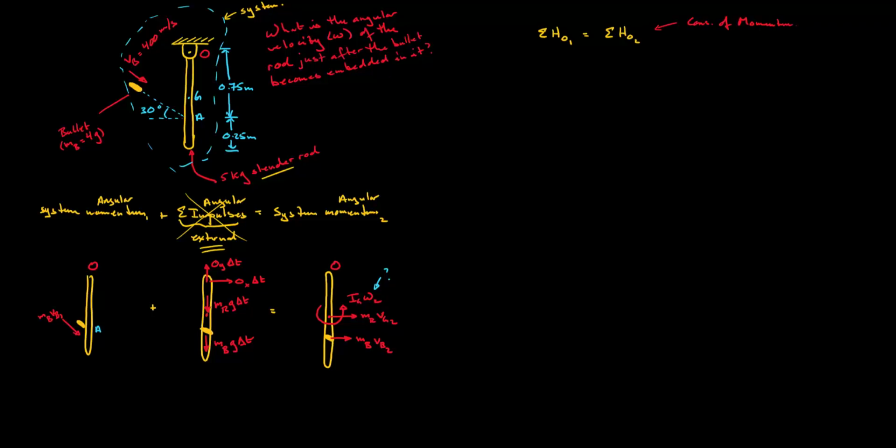Okay? So let's just stop here for a second. We're looking here at the impulses over here. Now, if we're evaluating our principle of angular impulse and momentum about point O, this one over here, we see that we have a certain linear impulse due to the weights. Neither of these contributes to an angular impulse.